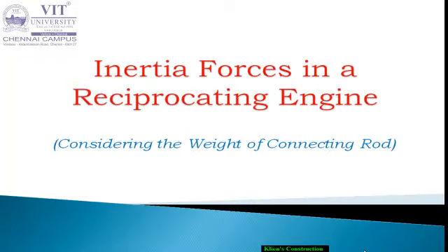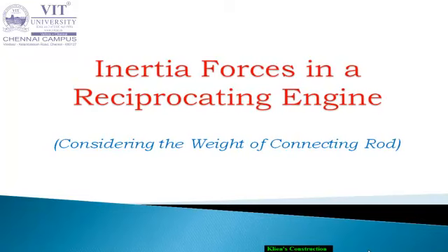Okay? The inertia forces in the connecting rod we are going to incorporate in this calculation along with the weight of the connecting rod. In the earlier analytical method we didn't bother about the weight of the connecting rod and the inertia forces of the connecting rod and crank. Okay, so here we have to consider the inertia forces of the connecting rod. So we have to find out the direction through which that inertia force will be acting, and also the magnitude of the inertia force we have to calculate. Fc component we have to calculate.